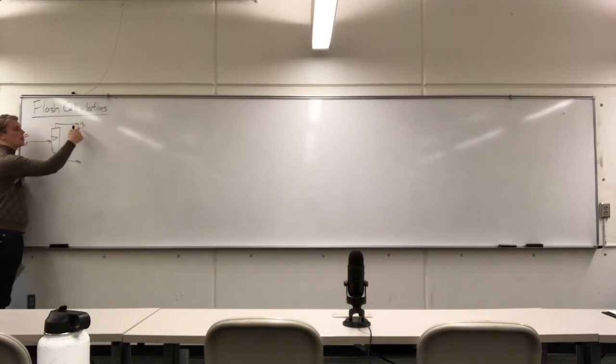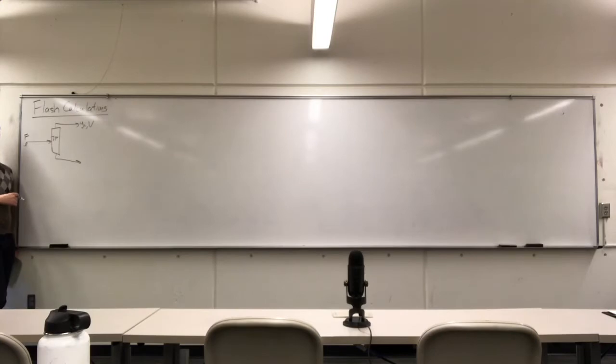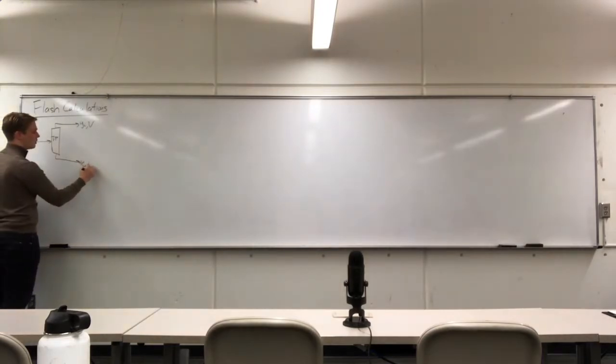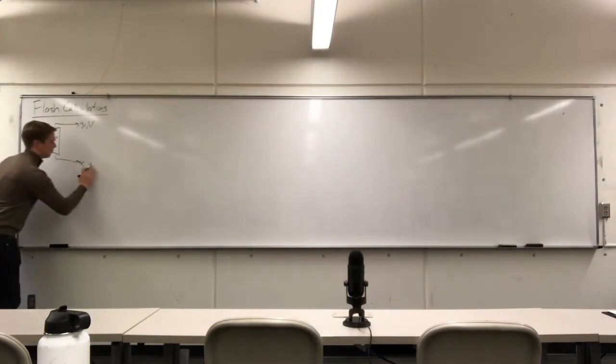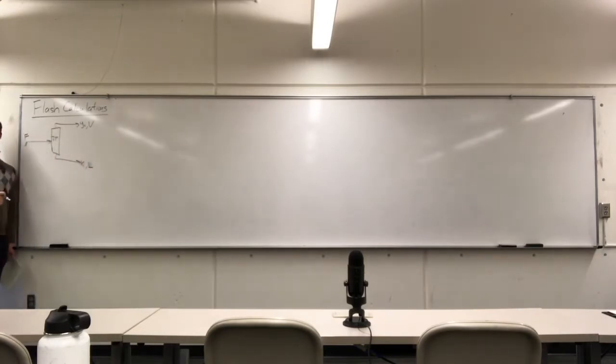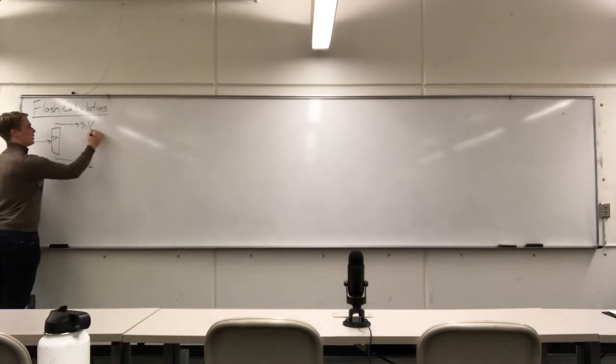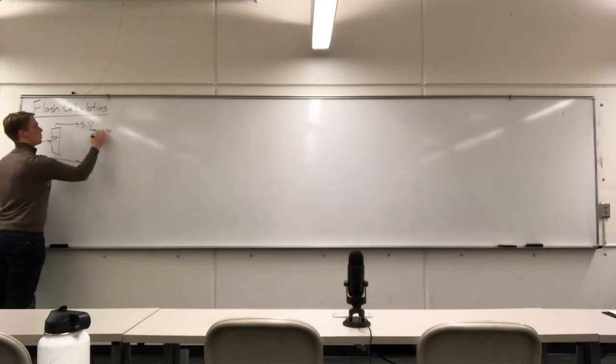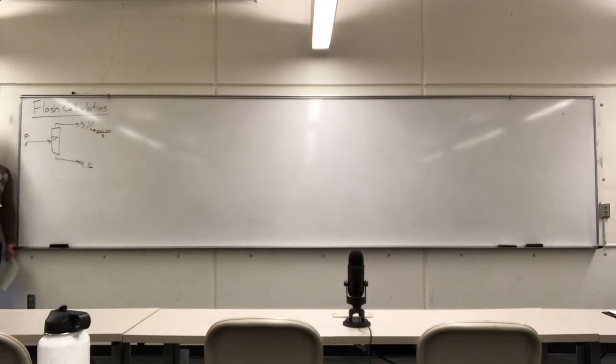You're going to get some composition coming out of your vapor phase with a total quantity given by V, either the mass flow rate or typically the molar flow rate, because that's what we use to do the calculations. And then coming out of the bottom stream, we're going to have a liquid composition and a liquid flow rate, where L, in this case, or V, would be moles of vapor per second, or whatever other units you'd prefer. These two streams are going to be in equilibrium. So the bulk of this calculation is in the fluid phase equilibrium part, right?